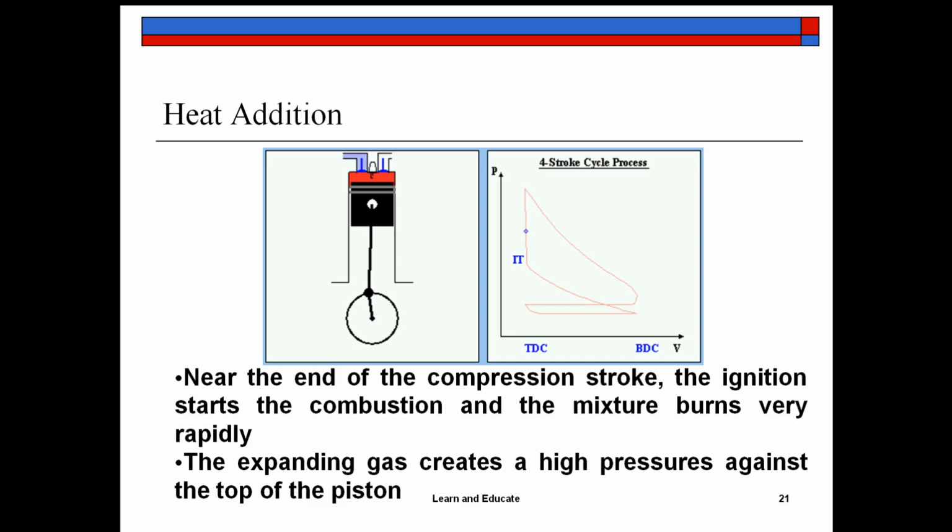So as a result of the spark created by the spark plug, what will happen? The burning of the compressed air fuel mixture takes place. The gas mixture starts expanding. The mixture burns very rapidly, and expanding gas creates a very high pressure against the top of the piston. So the piston should move downwards. There is no other way because both the valves are closed. So in order to take care of the increasing volume expansion, the piston will move.